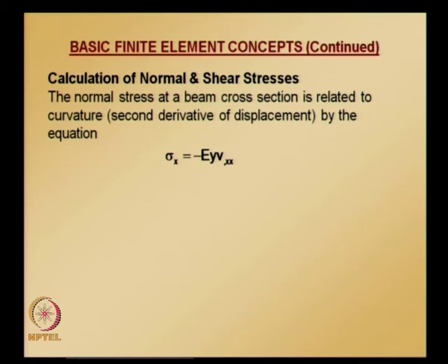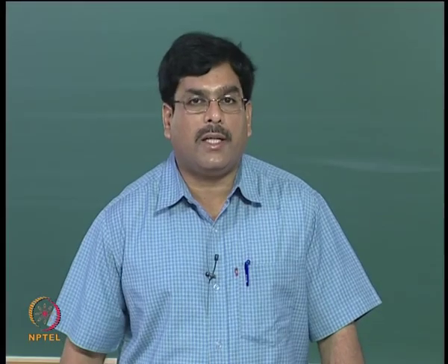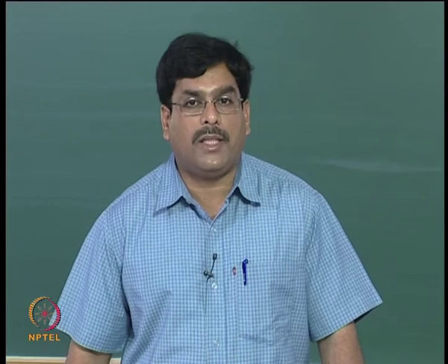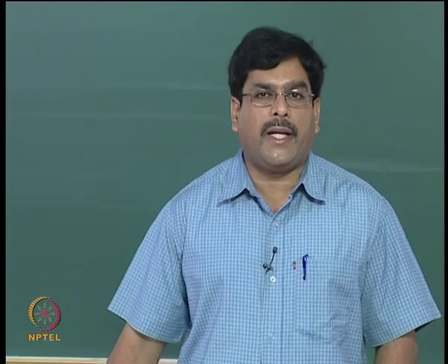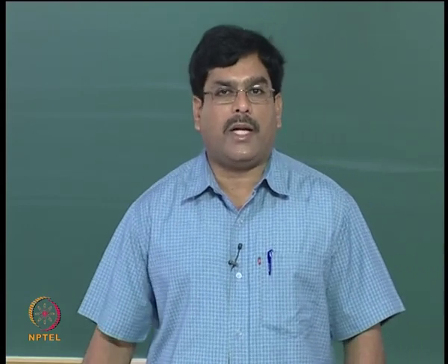using the assumptions of small deformation, and also the assumption that plane sections remain plane after bending. We obtained the displacement along the length of the beam in terms of the transverse displacement: u is equal to minus y times the second derivative of the transverse displacement with respect to x.